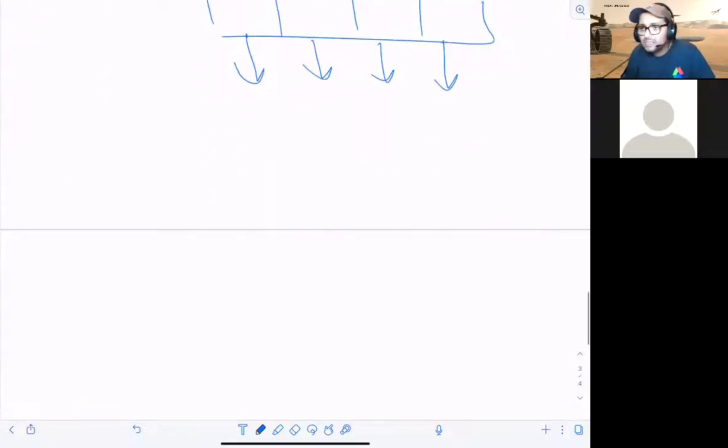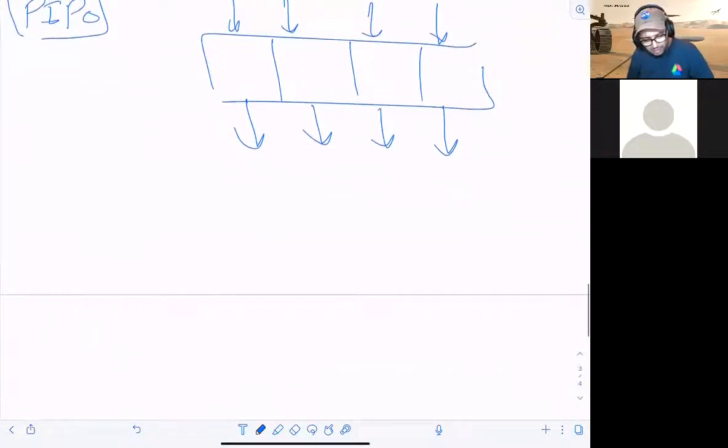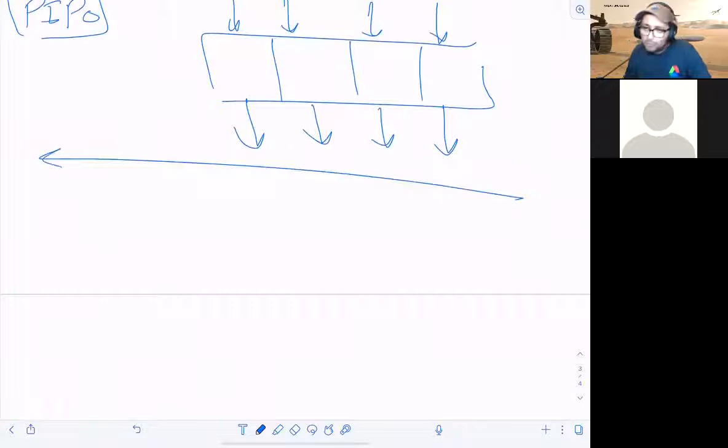So the Princeton University team came and said, if you're gonna perform such a kind of thing, why do you waste your time and use a sequential circuit? Why don't you use a combinational circuit? And in this case, this combinational circuit would be what? Registers. Sorry, multiplexers. So the element that's gonna be heavily used in a barrel shifter is a 2x1 multiplexer.